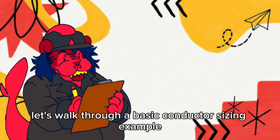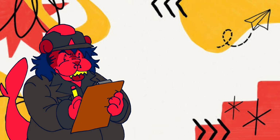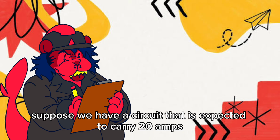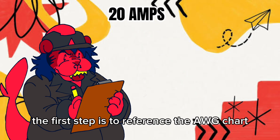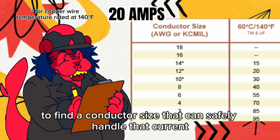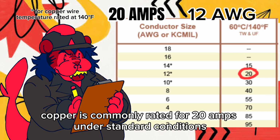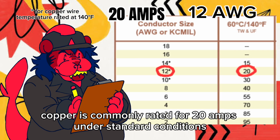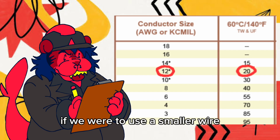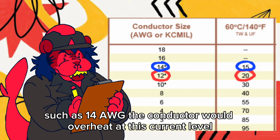Let's walk through a basic conductor sizing example using an American wire gauge chart. Suppose we have a circuit that is expected to carry 20 amps. The first step is to reference the AWG chart to find a conductor size that can safely handle that current. Looking at the chart, we can see that 12 AWG copper is commonly rated for 20 amps under standard conditions. If we were to use a smaller wire such as 14 AWG, the conductor would overheat at this current level.